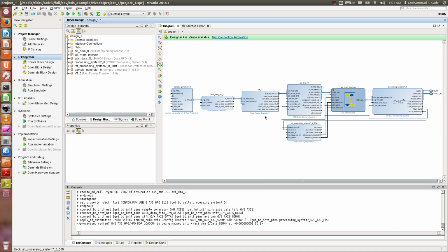What I do usually, I create one video pipeline, and then I create the TCL script, and then for the rest of the video channels I replicate just the commands inside the TCL script, and I change the instance name. This way I can create complex architectures very easily using the TCL. So the TCL is important. And now I come back to our story here.